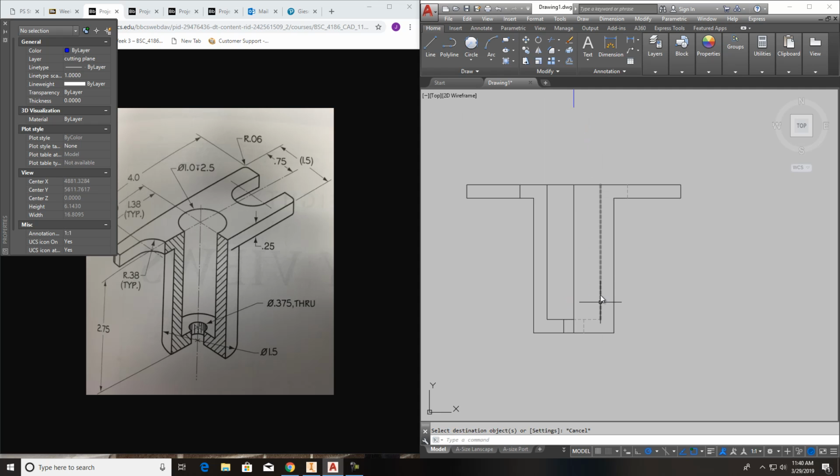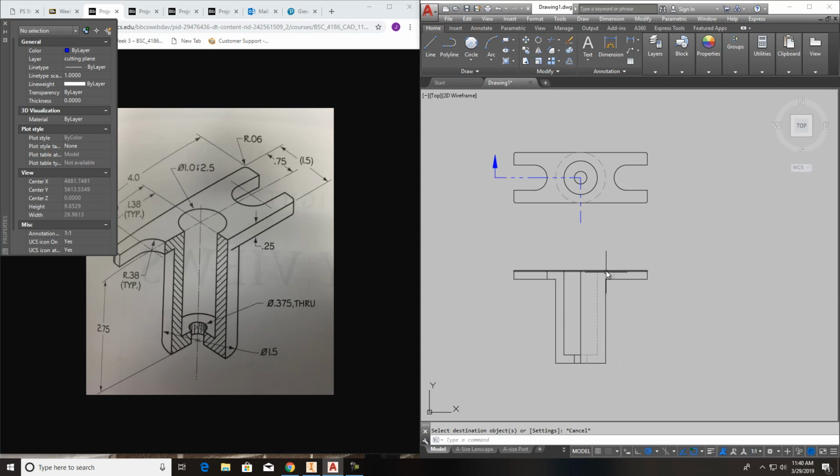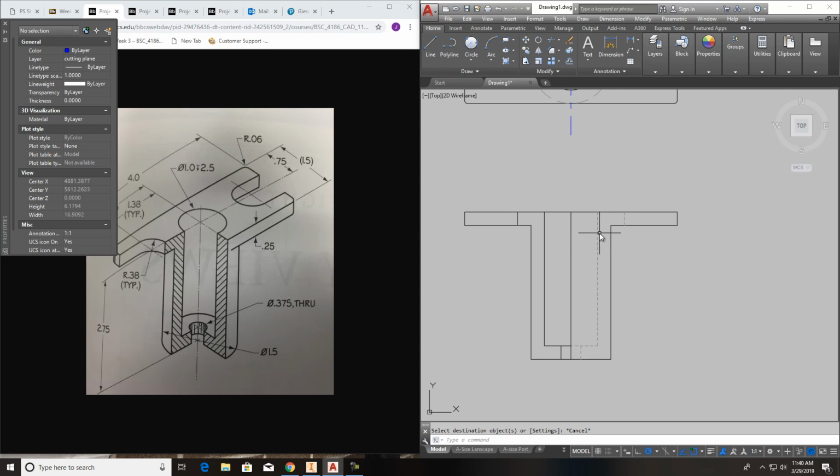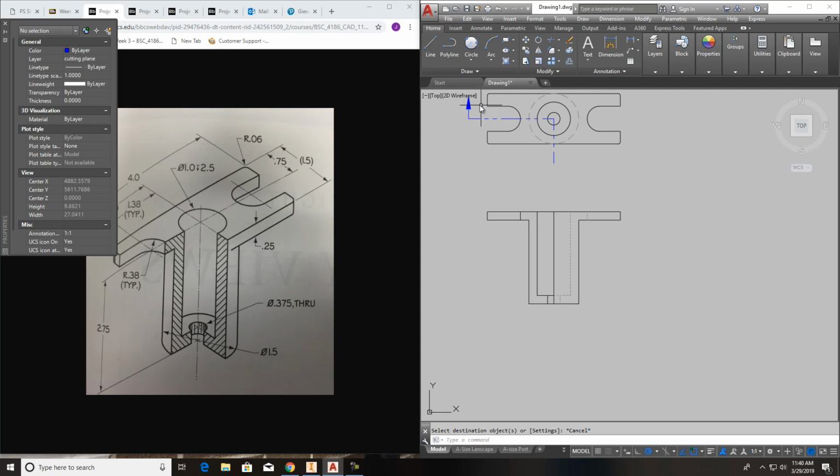So this side over here didn't get cut, so whenever it rotates down, it's still going to look like its normal orthographic projection with hidden lines in it. Now, over here, this has been cut. Anything that this line cuts is going to have section lines. So as it comes across from here to here is open, so there'll be no cuts here. It'll start from here to here will be cut, and then down at the bottom, it'll come over to that hole, and it'll stop right there.